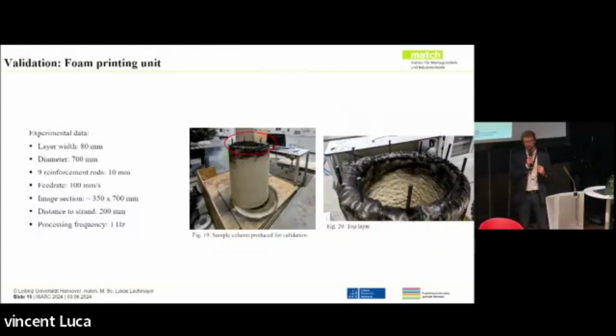we conducted our first inline measurement experiment. So again, we printed one of the foam columns, we painted it black, we inserted the rebar, and then we used our system, like the Dörrie robot attached with the measurement unit, and moved one circle on the top. We fulfilled one circle. Processing frequency is about 1 Hertz for getting the image, running it through the convolutional neural networks, and getting out in the end the depth pixels that we want to have.